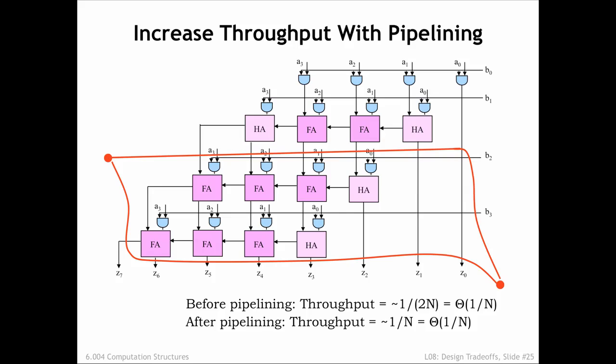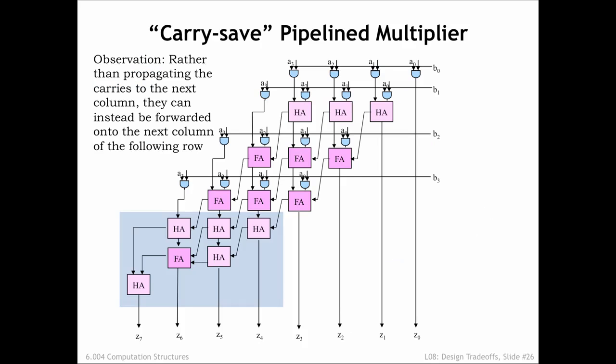Is there any hope of a dramatically better throughput? The necessary insight is that as long as an entire row is inside a single pipeline stage, the latency of the stage will be order n, since we have to leave time for the n-bit ripple carry add to complete. There are several ways to tackle this problem. The technique illustrated here will be useful in our next task.